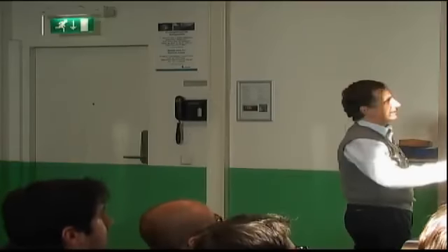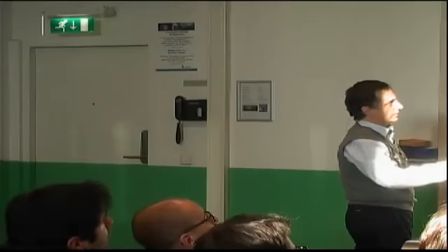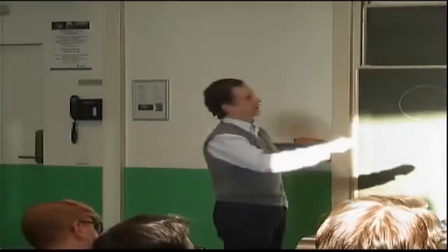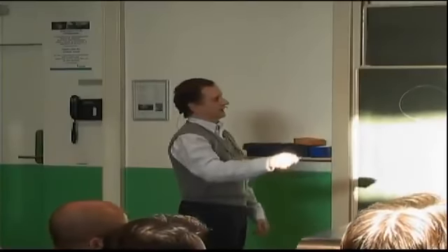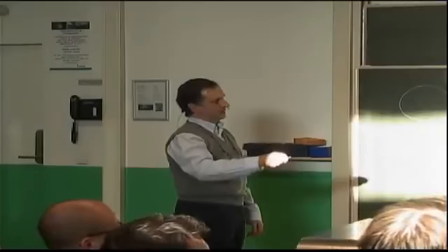Or I could have a plate with 2 stiffeners at the edges, so now it's the same as this one, but imagine the inner layup extending all the way to the edges, so the green part. The outer layup will be the 2 stiffeners plus the skin. So this would be my outer layup, and the inner layup will be the center portion shown here. Or I could reverse that and end up with the stiffened portion in the middle.